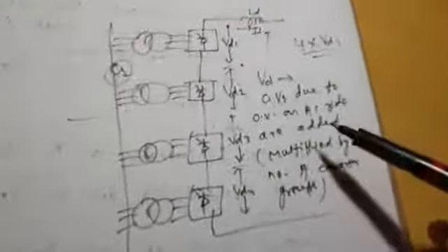Next is because of sudden loss of load. Just like in AC systems, in HVDC system also a loss of load may result in overvoltage. And finally, switching, another cause for overvoltage due to disturbance on DC side is because of switching of DC filters and parallel connection of poles.